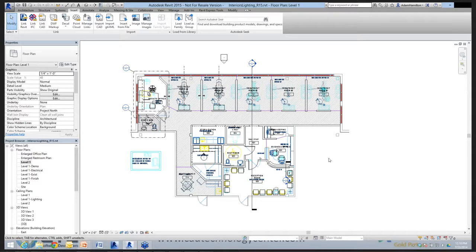The other thing that's important to know is many people who open up the default template, the default architectural template, realize that there's only one floor plan per level, and that a lot of people try to stick a lot of information inside the one view. And it's important to note that Revit isn't all about singular views. The intent of Revit is a big empty room, and we're building our building inside it, and there's different ways of seeing, different ways of slicing through that singular model to display the information we want to see, and that's a lot of what we're going to be talking about today.